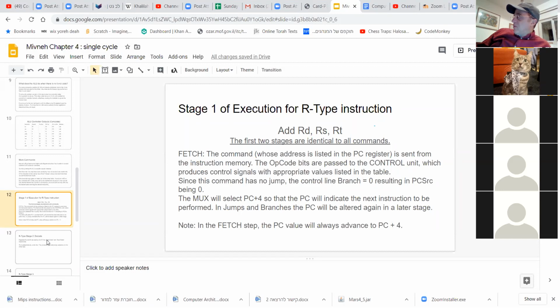So if we're just at the edge, if the PC is 0 followed by all Fs in hex, I'm going to have to grab that 0, and if I want to go 1 step forward, I can't, because 1 step forward means the location would be 1 instead of 0, and then 0, 0, 0, 0, 0, 0, 4, let's say, or 3. I can't go there because the PC won't let me. The PC is stuck at 0.